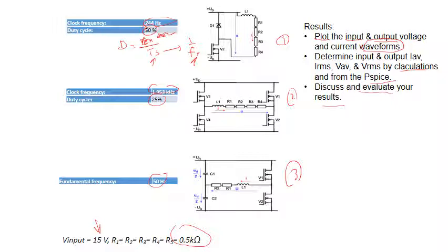Okay. Now in this circuit, when we put the resistances together, you can add them and come up with our total resistance. This is the R load, and when the switch here conducts, this diode will not conduct, so the current will flow here through the switch back to the supply. Let me change the color. When the switch is off, the energy stored in the inductance will be released. We talked about this in the first live session of the lectures.